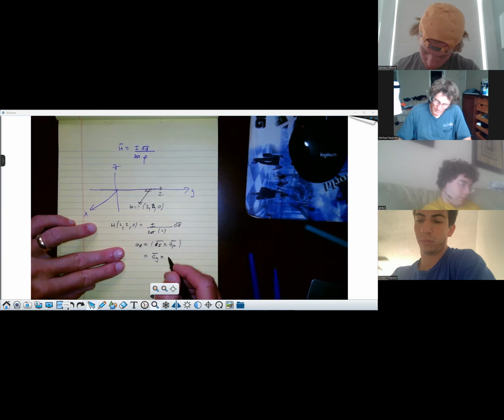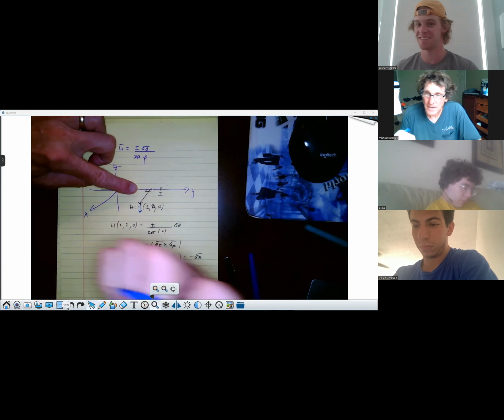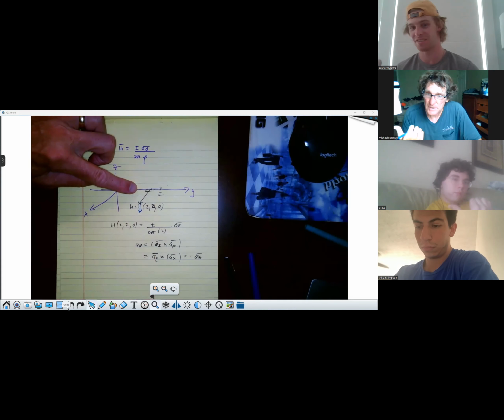Now, how else could you get it? Remember I told you the right-hand rule business. You use this all the time. If you take, hear me now, your right hand, put it in the direction of the current, your fingers curl around in the direction of the H field on your right hand side. Technically, if the current's going this way out, my fingers curl around. Come right here and look. Right here, you see how it's pointing down? Put your right hand in the direction. You with me on that, class?